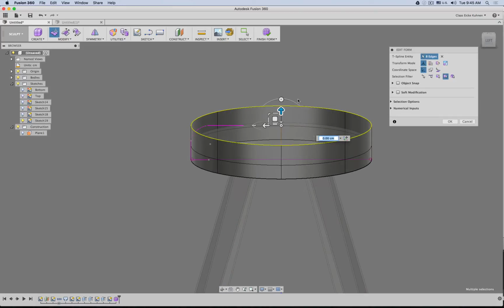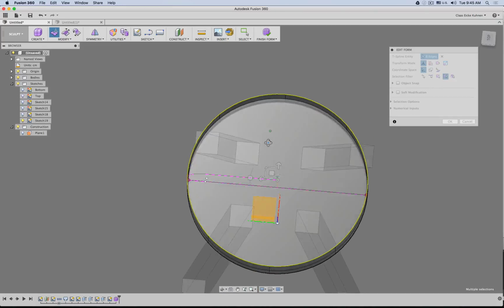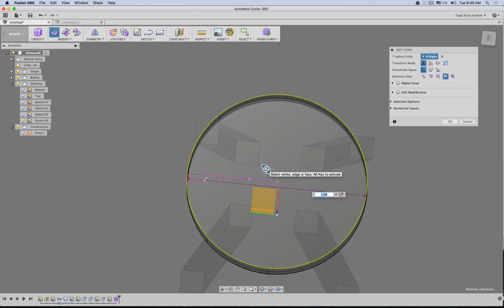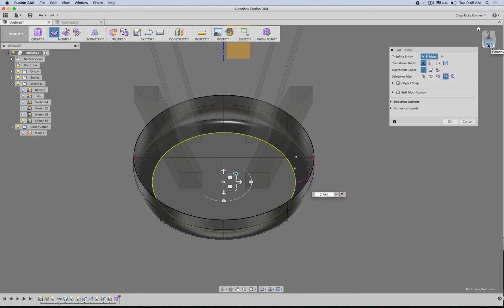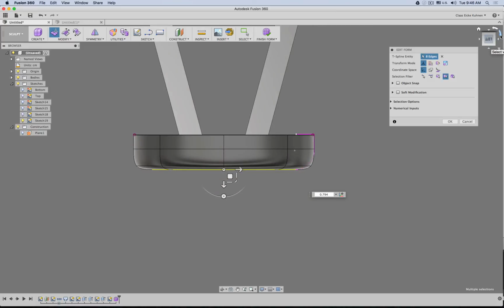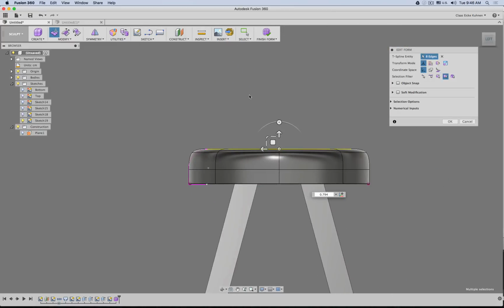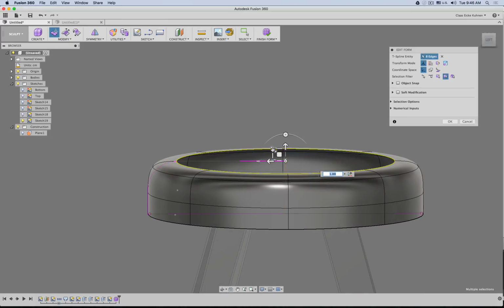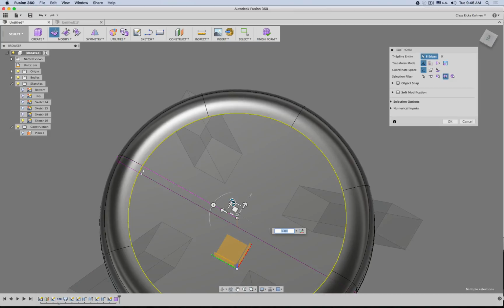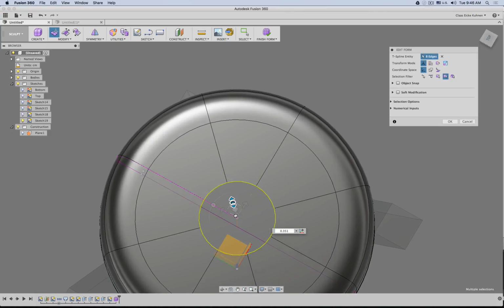Okay, now press the Alt key and then in top view make sure you click on this center, scale. Now we can scale this in. Whoops, wrong one. Okay, yeah, I see now we have a nicer shape. Maybe Alt and one more extrusion.